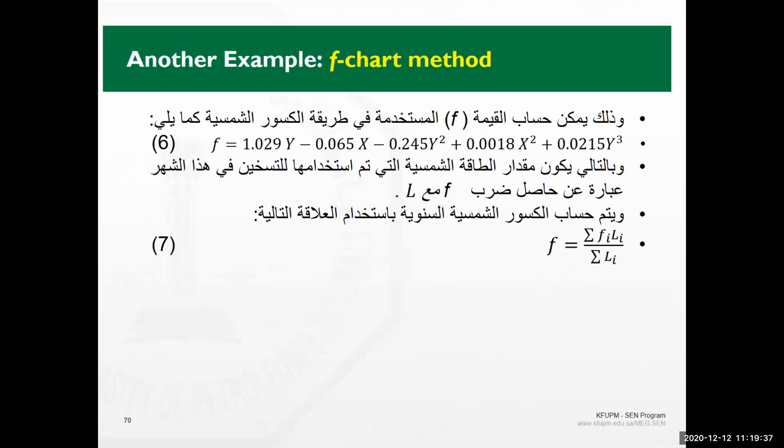And accordingly, this is the F equation, which is used for air or water heating, and at the end to calculate what we call the solar fraction. The annual solar fraction represents how much of the total load that you have is going to be taken care of by the solar collector, so that the remainder will be taken care of either by electricity or by a boiler with diesel fuel or whatever it is.